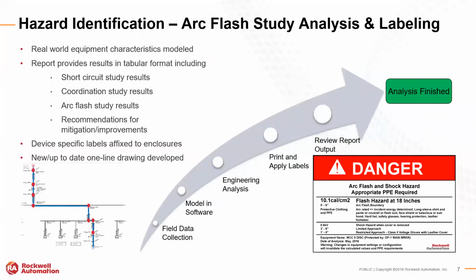So the next thing we're going to dig into more thoroughly is what's a good practice for getting an actual arc flash study performed. There's two standard methods for generating arc flash labels and determining PPE requirements when working on energized equipment. The first method is called the PPE category method, which is also referred to as the table method. You may have heard that terminology before.